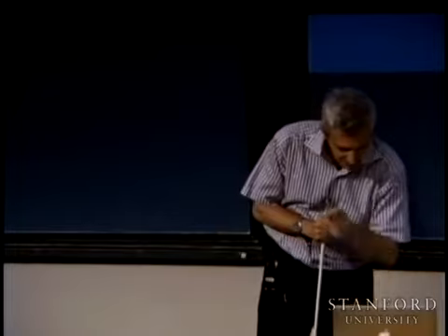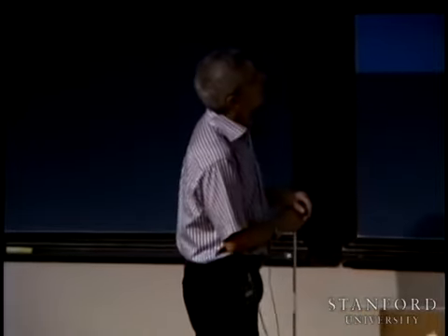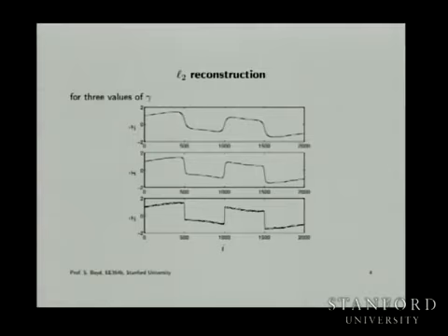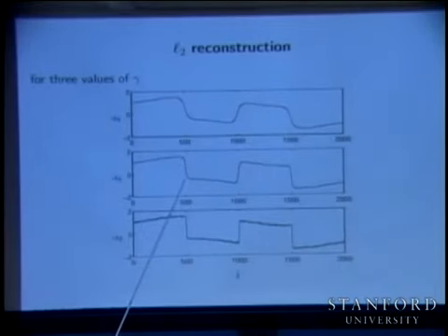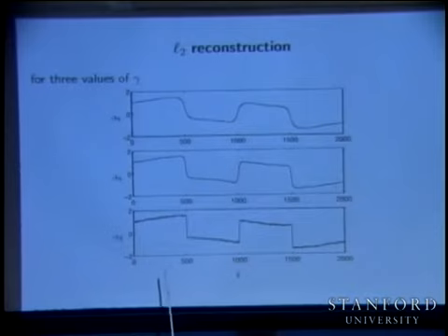Okay. Here's the L2 reconstruction, just to give you a rough idea of what happens. In L2 reconstruction, to really smooth out the noise, you lose your big edge here. And this is maybe the best you can do with L2, the best trade-off. In this case, that edge has not been preserved exactly. It's actually been smoothed a little bit. You just can't see it here. And here you're not getting enough noise attenuation. So just to get a picture.